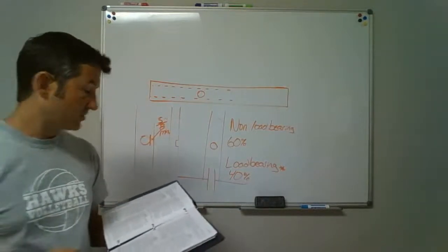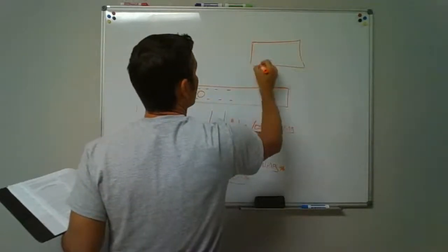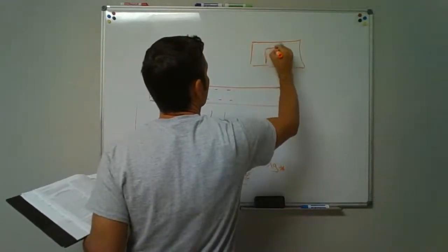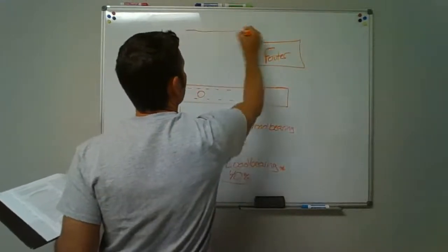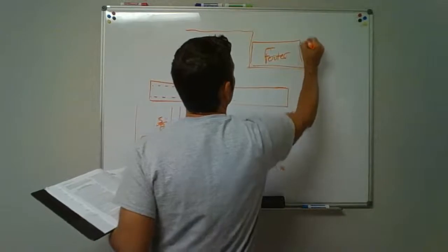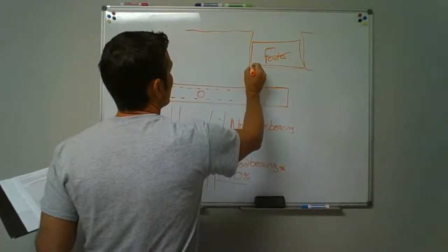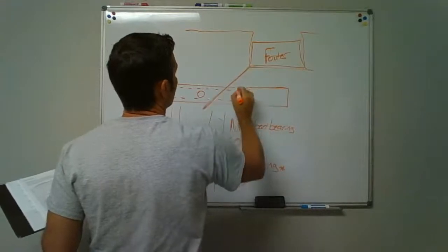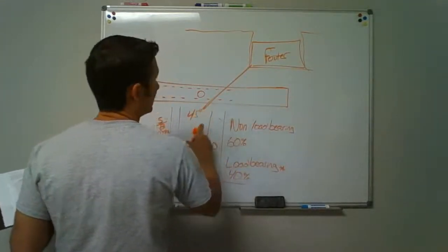Protection of the footings. We showed you the footing before. Remember, you drilled the footer. Remember how the ground level was up here? We dug down, put the poured concrete footer here to protect this, at a 45-degree angle away. That's at a 45-degree angle.